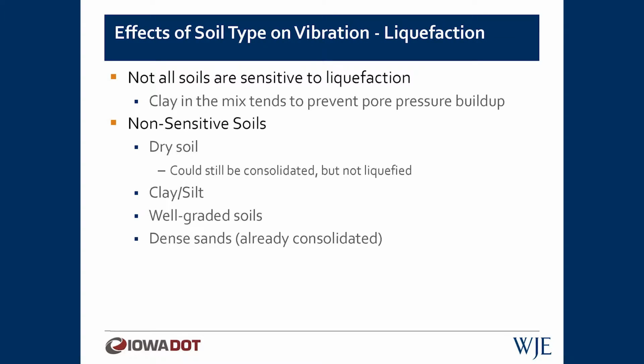There's a commentary in the research that when you add clay to the mix, it tends to prevent the pore pressure buildup. And then, because I've already covered the sensitive soils, non-sensitive soils would basically include dry soils, which would be loose sands. They are not necessarily liquefiable if there's no water present. Even partially wet sand is not as sensitive as a saturated sand.